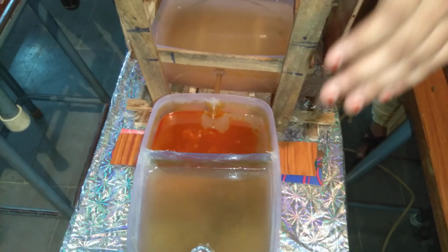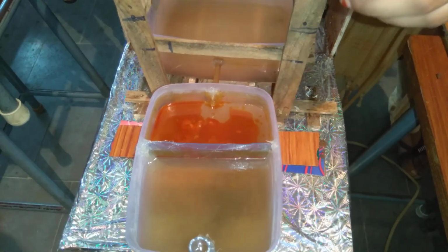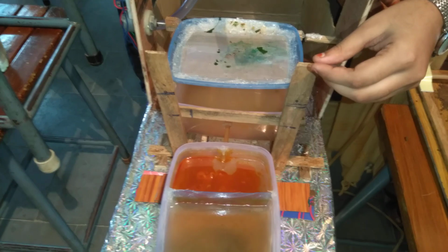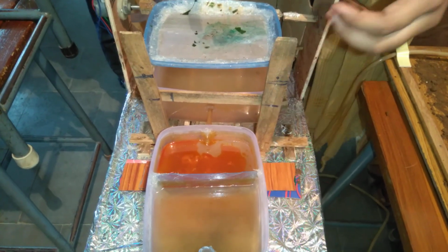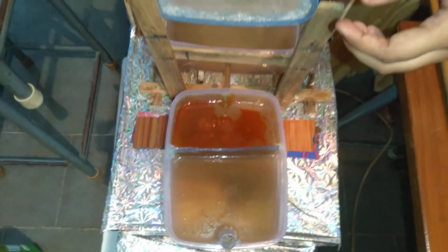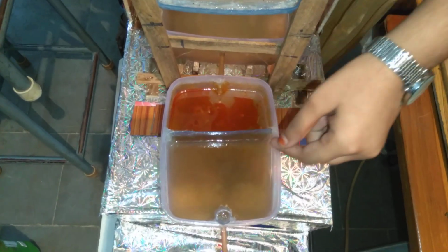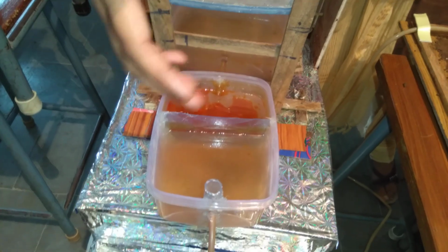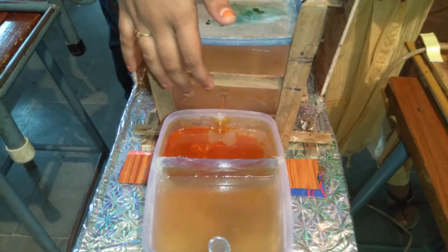So the solids which have not escaped in the first process are sedimented over here, and then it goes to the oil treatment plant. Here this tank is built in such a way depending upon the property of the oil. Oil has the property to float on the surface, so it cannot escape into the other column. The water which is free from oil will come from the bottom level and go to the next level. Here you can also observe the turbidity, that here it is more and here it is less.